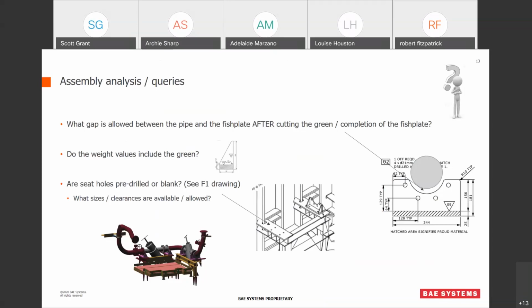Yeah, sorry, Rob, just to back that up. So if you get 25, okay, yeah, so there's like 25 mil of green material. If we were going to try and take a measurement so that we could pre-cut the flange, if that gap had to be a certain min or max value, that would tell you how many increments you would have to have, because you would want to cut to maybe a standard size, so either take 5 mil off or 10 mil off or 15 mil off. You wouldn't want to have to remove a precise 12.5 millimeters of green.